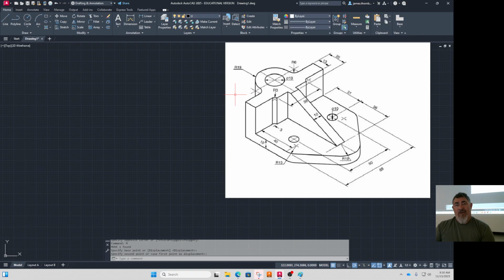No, it doesn't matter. But I'm going to have to offset it a few times because I need to go from the center. I need to go 6 from the center line to here, right? Then I need to go 13 from this line to this line. And then I come straight down. I need to go 31 to there, and then 36 to there. So that's 67 from this edge to there. So I've got at least 1, 2, 3 offsets I need to do.